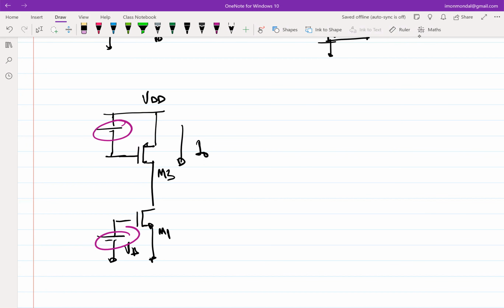So now, if you want to do that, what is the problem that we faced for NMOS biasing? Constant voltage biasing: two independent sources fighting each other. Then your small signal parameters are not particularly constant with respect to ambient changes and so on and so forth. So you want constant current biasing. For constant current biasing, we do a whole lot of things, right? We spent more than enough time on that.